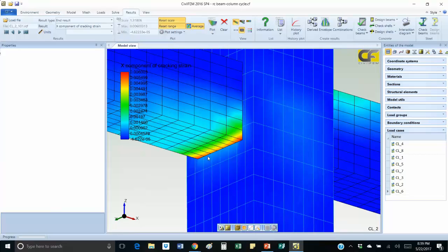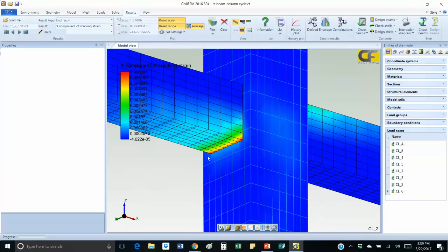As we already know, there are different models and different methods for capturing the plastic or inelastic behavior, but sometimes the plastic hinge method has to be calibrated with real tests or real models. Because plastic hinge models can capture the inelastic rotations, taking into account the degradation in elements due to crushing and cracking, but the power of this kind of model, distributed plasticity, is that we can get the exact point of initiation of cracking or plastic or inelastic behavior.